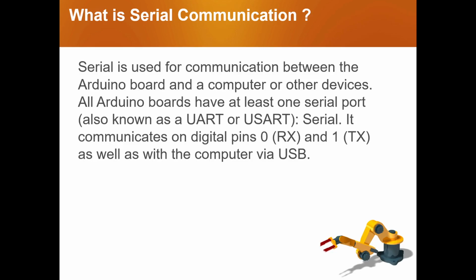So what basically is serial communication? Serial is used for communication between Arduino board and a computer or other devices. All Arduino boards have at least one serial port, and these are also known as UART or USART. Serial communicates on digital pins 0, called Rx, and 1, called TX. And we can also communicate using our USB through our computer board.